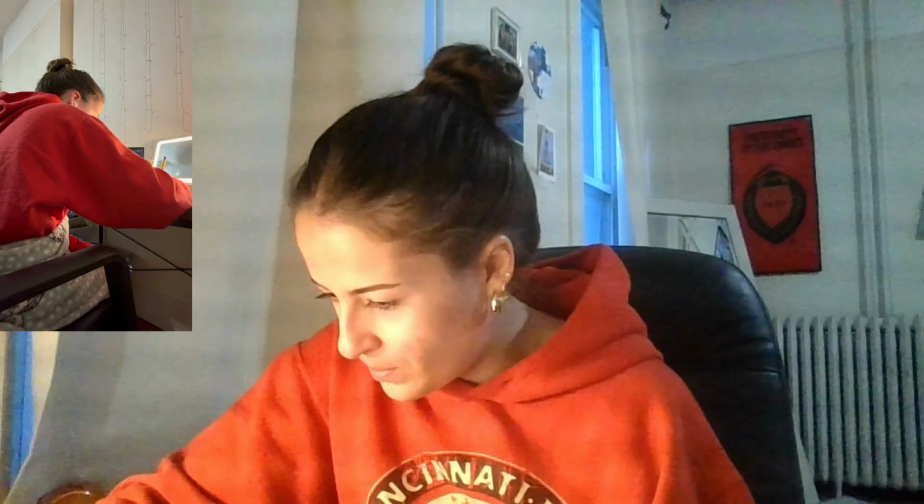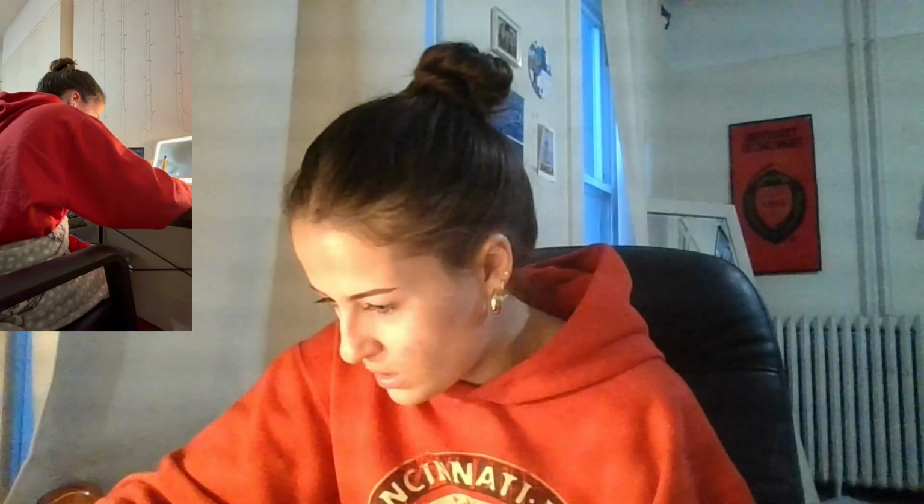For the mole fraction, we're talking about the mole fraction when those three components are intermixing, so they're going to be gas, which means they'll have the variable y for their mole fraction. So y1, which is once again our acetone, is going to be assigned a value of 0.319. y2 will be 0.528.